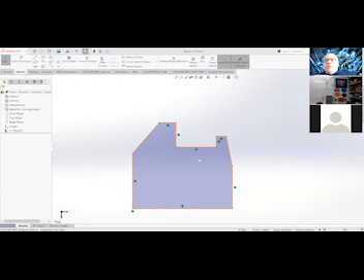Okay, now when we were doing our drawing in AutoCAD, we had to put in all of the sizes as we went. When you put a dimension or a size, that's also a constraint. Let's see if we have a question or two before we jump forward. So dimension is also a constraint that keeps us in place.